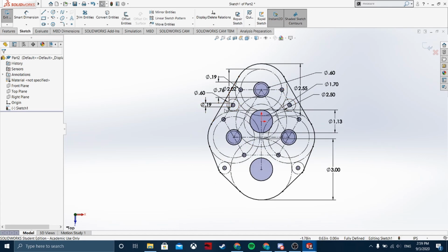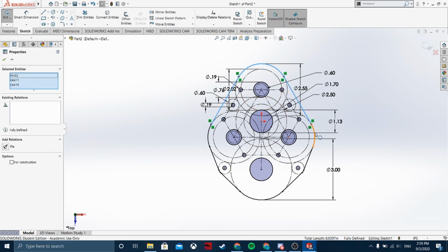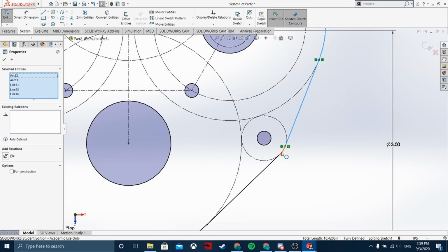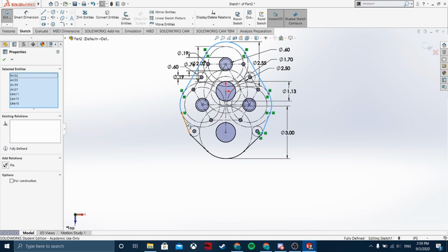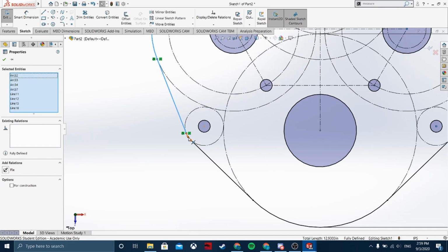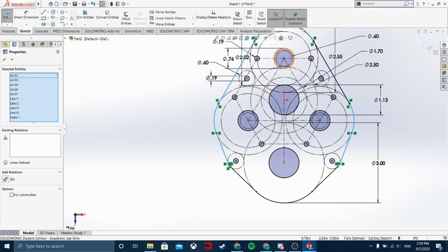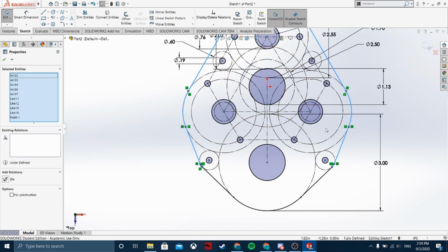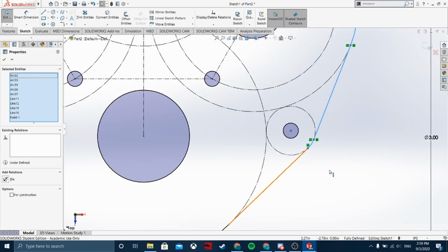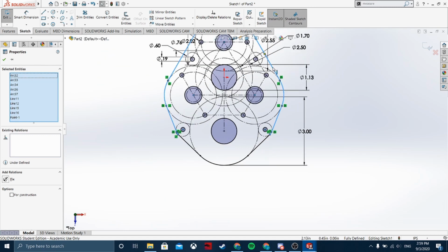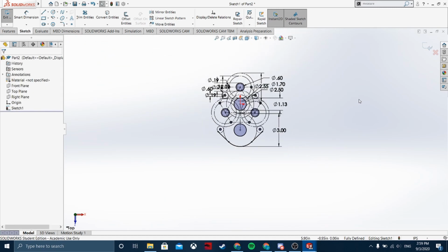Now for the second plate, I mean, we could just use the exact same plate, but we're gonna go the extra mile and cut it down some more just to save weight. So what I'm doing right now is I'm highlighting these outer lines and arcs that we don't need, right? Because for the second plate, we don't need pinion holes, we don't need motors, right? But we still need the 60 tooth gear and we still need the stand-ups, so that's why I'm keeping these two lines and this arc here. So I'm gonna right click this and delete all these things.